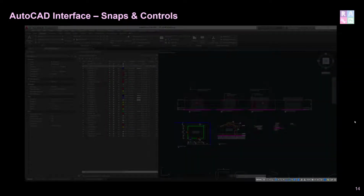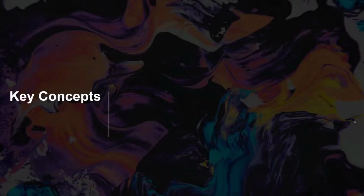And it's in this space where you actually scale the drawings to the appropriate sizes and arrange them on the sheets. In the bottom right-hand corner, you would have what can be classified as snaps and controls. These are controlling actions for the detail in which you actually model and draw. So, you have grid controls, whether you want to see a grid that can assist you, whether you want to draw just orthogonally in 90-degree intervals. You've got polar tracking, which will snap to certain directions, and then you have object snaps, such as being able to snap to endpoints of lines, midpoints, tangent, quad, etc.